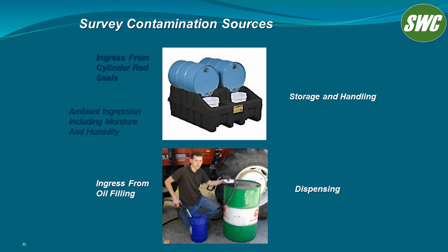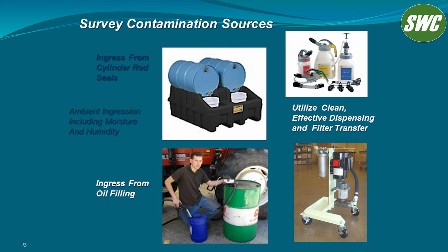This young man's really proud of how he's dispensing this system, but it's not the proper way of doing it. Rather, you want to utilize clean, effective dispensing and filter transfer devices.